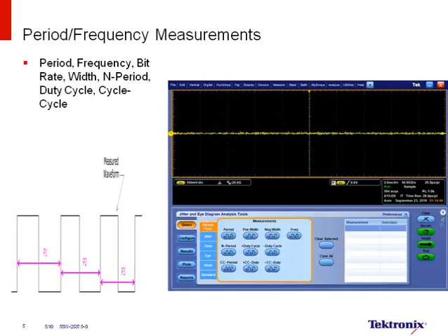In applications where both edges of the clock or data are used, the width and duty cycle jitter measurements are required to ensure timing balance between the positive and negative clock edges. In PLL-based systems, N-period or N-cycle measurements can be used to look for periodic variations in the systems. Cycle-to-cycle measurements are useful to ensure adequate setup and hold timing between consecutive clock cycles. Cycle-to-cycle jitter analysis can also be used to measure high-frequency cycle-to-cycle modulation within an SSC or low modulation system.